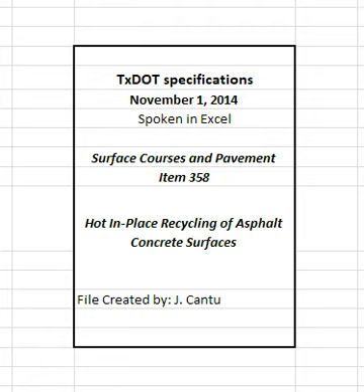Remove grass and other vegetation from the edge of the existing pavement to prevent contamination of the recycled bituminous material during this operation. Use the milling heads to remove a minimum of 3 inches laterally of the completed adjacent pass and make a square vertical cut in the heated material to achieve a hot bonded longitudinal joint. Ensure all material across the full lane width is processed between consecutive lane passes to assure any wedges or slivers of unprocessed materials are not left untouched by the milling heads and covered by the recycled material, unless otherwise approved.